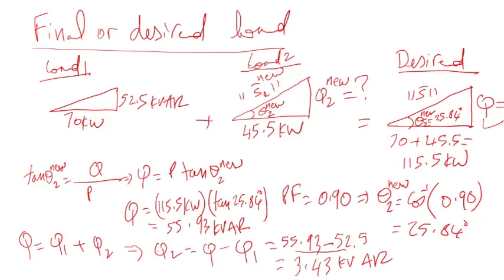So this is the new reactive power that the motor would have to supply in order to correct the power factor to 90% lagging.